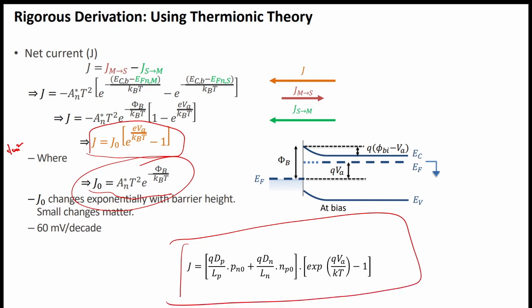How is this metal-semiconductor junction different from the PN junction? In the PN junction diode, the reverse leakage current can be controlled, and that can be very less. But in the metal-semiconductor junction, the reverse leakage current is very high, in microamps, and in the PN junction it is in nanoamps or lesser, in picoamps also.